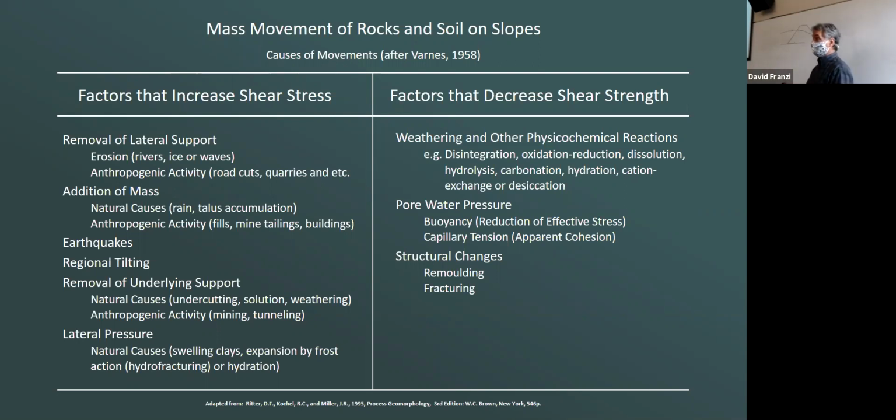So primary minerals that were providing cohesion, that were providing internal friction, they're weathering. What do they weather to? Clays, right? You take a feldspar and you weather it, you end up with a clay as a residue. And so slowly over time, the internal friction and cohesion values slowly deteriorate and change.